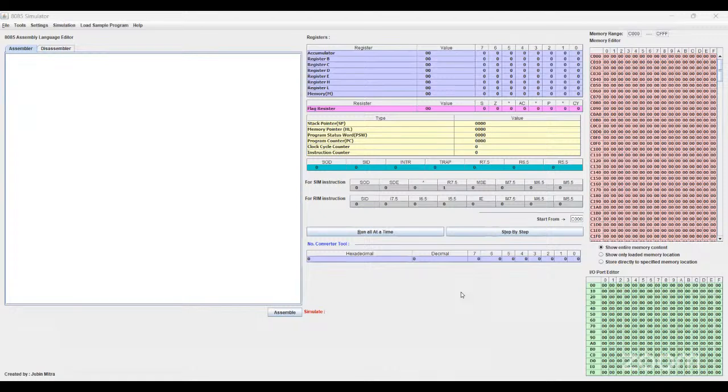In no operation, there won't be any activity. It just leaves that and then it jumps. This will be useful when you want to modify the main program: instead of changing the addresses, we can use this NOP so that there won't be any change in the program. Then halt enters the halt wait state. This is the end of the program, we write HLT.